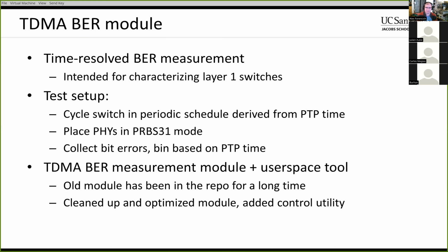And the idea with this module is it's intended for low-level link-level characterization of layer 1 switches. I guess you could use it for electrical switches, but it's probably more useful for optical switches. And basically what you can do is synchronize the switch with PTP time, and then all of the NICs can derive a schedule from PTP time and use that to control the binning of the collected bit errors.